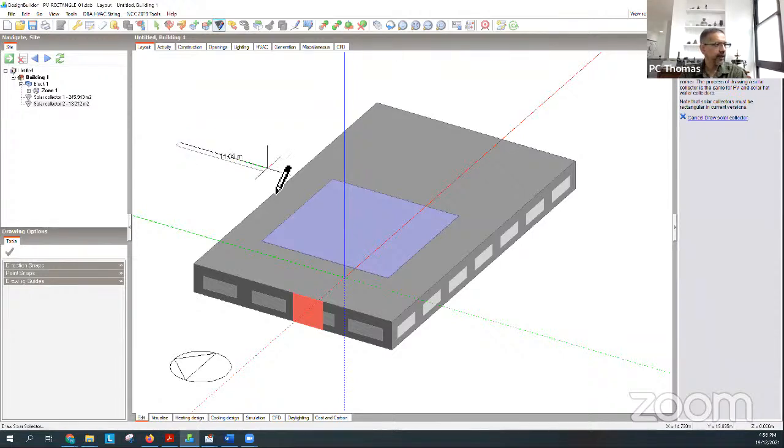You can draw a panel, and then you can even tilt it after you've drawn it. So you can have a whole series of tilted panels providing input to the building. You just have to give it the correct generation name, generator system type, and all that. So I don't think that should be a problem.